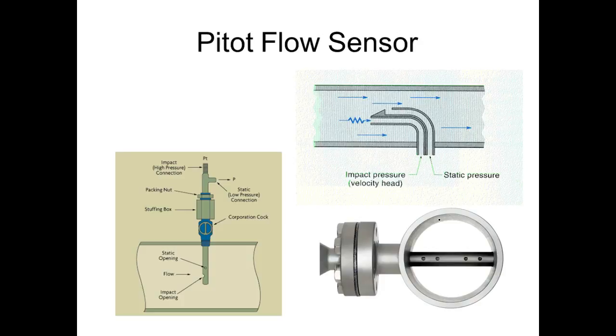They'd get out there, and they had to put covers on them all the time because dirt daubers like to build nests in our pitot tubes. So that was one of the things you covered up. And the static tubes on the side, you had plugs you would put in those when the plane was on the ground. And what part is exposed? The pitot tube is exposed.